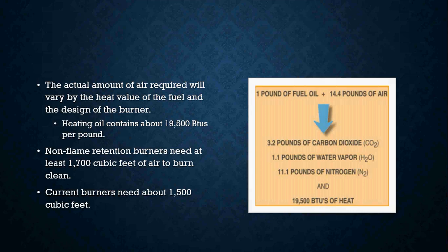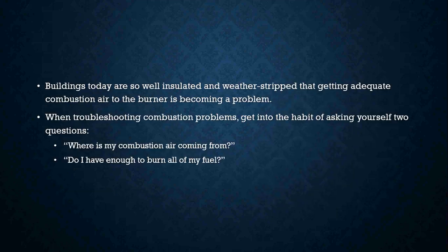Non-flame retention burners need at least 1,700 cubic feet of air to burn clean. Okay, current burners that we are dealing with need about 1,500 cubic feet of air. We have to take building construction into consideration when we are setting up and thinking about combustion and how these burners are set up today.